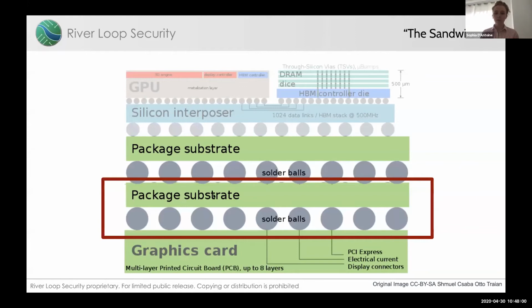Additionally, when you look at this sort of component through an X-ray, the solder balls mask things, and there's actually no footprint through a traditional X-ray, or how you would traditionally look inside of a chip. So yeah, the pro of this attack is that it's logistically easier than wire-bond implants. And there's no real package to reverse engineer.